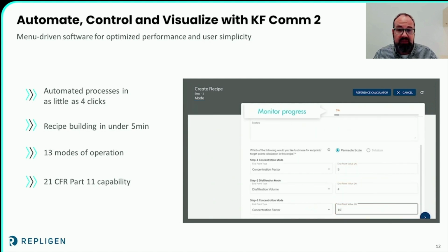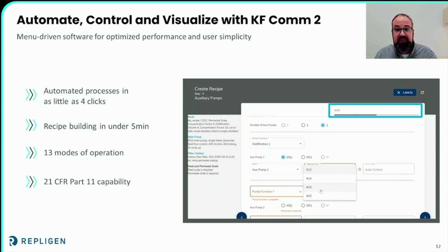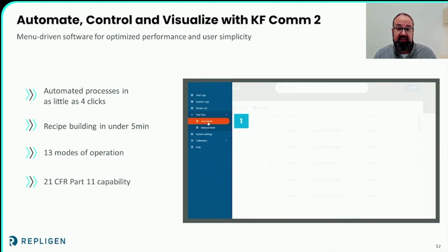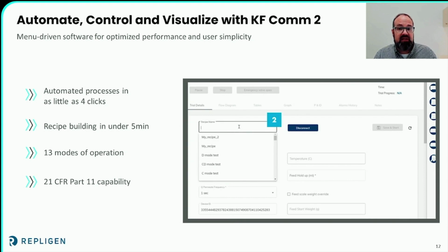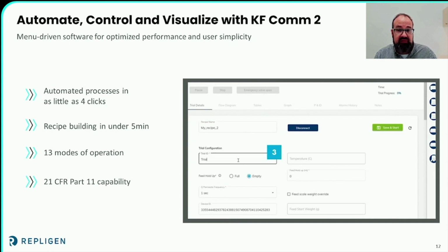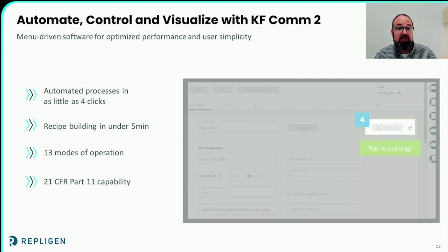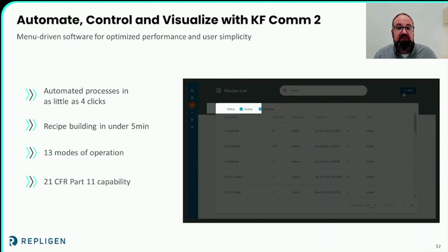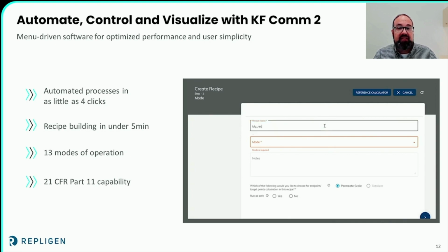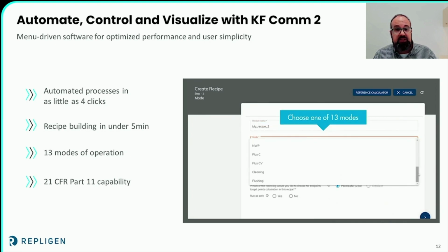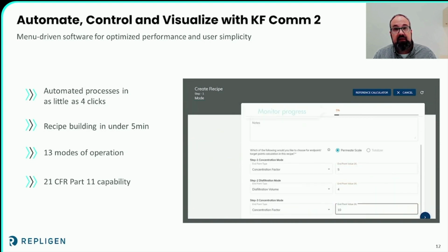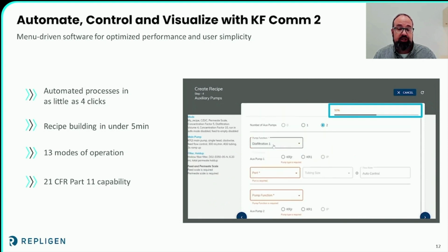The software also enables 21 CFR Part 11 compliance with the same package and does not require additional equipment or software add-ons. Some competitive systems, on the other hand, don't even accommodate all the basic TFF applications or lack recipe editing capability within the software, which allows you to determine your endpoint values. And 13 modes of operation is nothing to laugh at. This extensive library of modes allows you to deep dive into all phases of TFF, from flushing membranes to optimizing processes through a flux excursion mode.